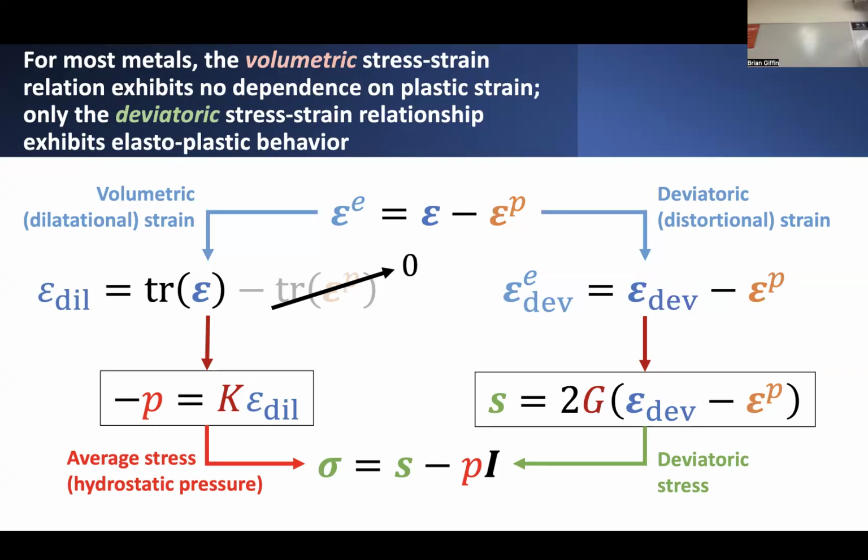It just goes away, which suggests that the dilatational portion of the material's behavior overall really only depends on the total strain in the material. It's only the deviatoric portion of the deformation that contributes to changes in the relative deviatoric stress that results.